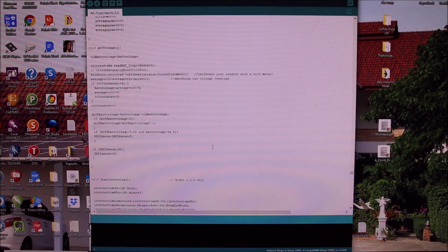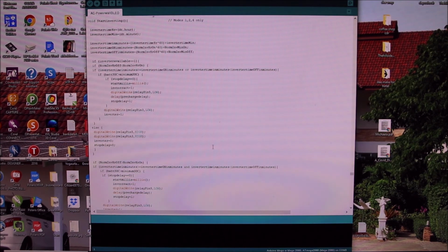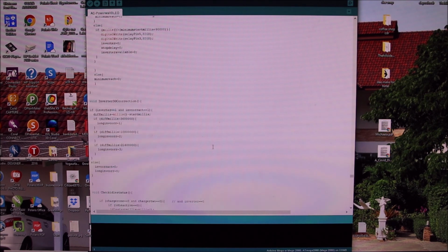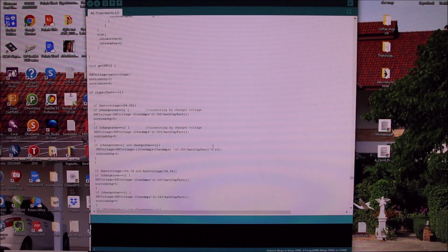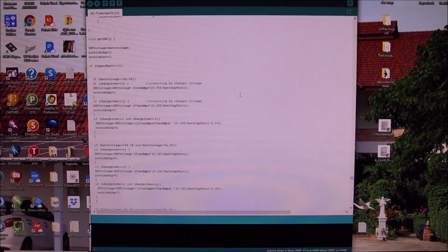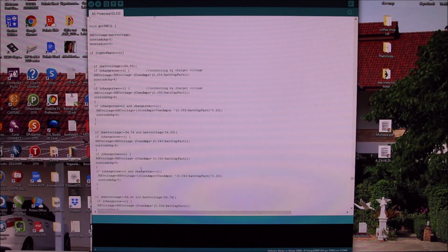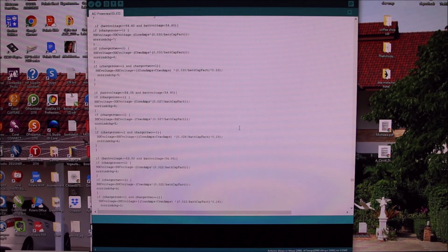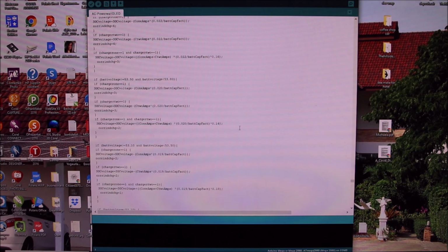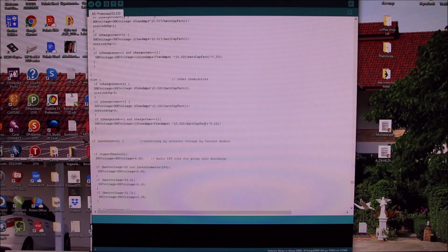All the calculations, voltages, there's a lot of functions going on. And the longest one is, of course, the state of charge, but this is only because the chemistry of lithium iron phosphate is so extremely intense to predict. And there's, you see, tens of if-then conditions to be handled, with two chargers.